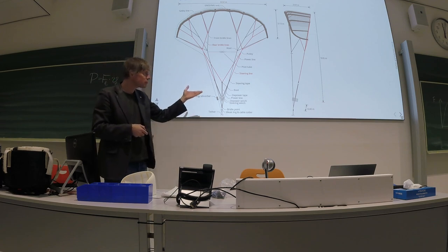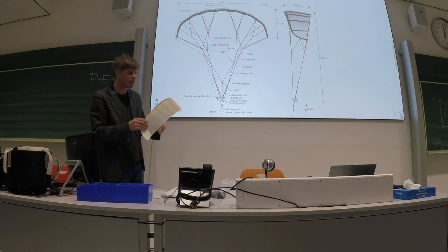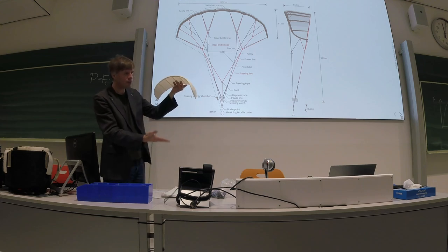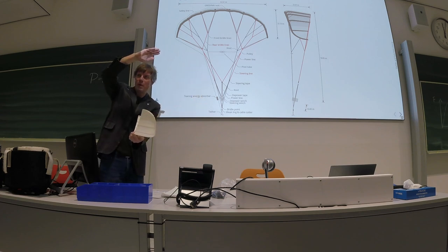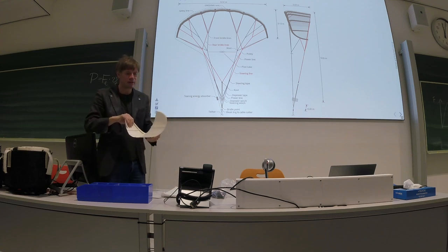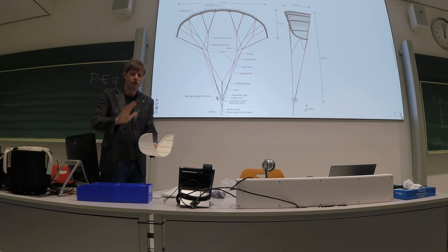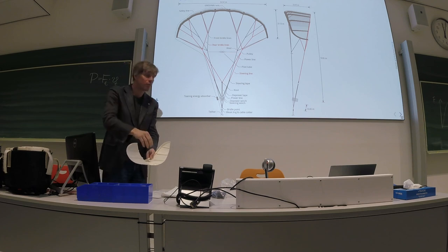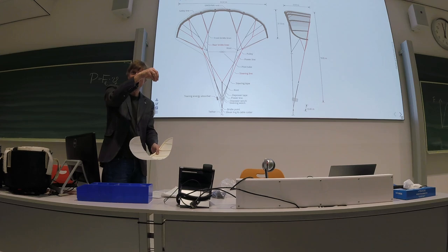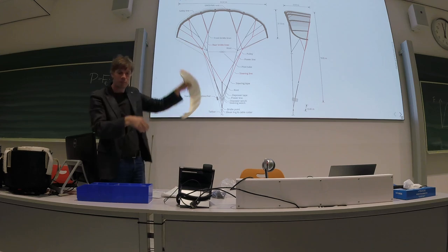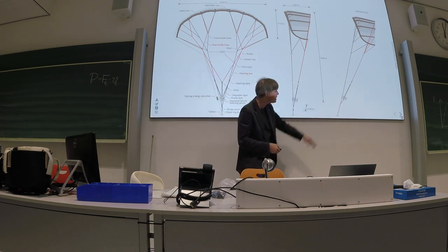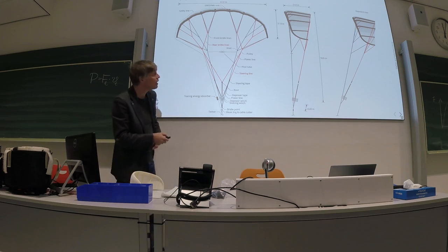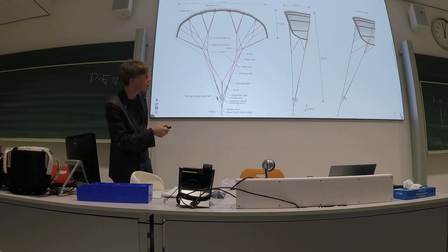This kite, and the whole setup, was actually optimized for a very short distance to be able to hang it upside down from a mast. So that was one of the design criteria here, to have a short mast, to be able to hang it from the mast. The kite control unit is then at the mast top to launch from an upside down position. We will see this later.